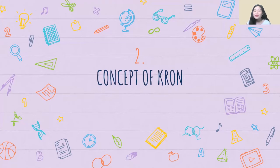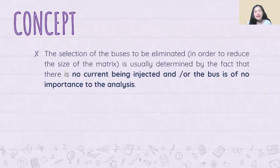Now we have to move forward to the concept of our Kron reduction method or process. The selection of the buses to be eliminated in order to reduce the size of the matrix is usually determined by the fact that there is no current being injected and/or the bus is of no importance to the analysis. Alam naman natin that our sole purpose of having the Kron reduction is to eliminate a node, or a bus, or a part of our matrix to be able to reduce its size.